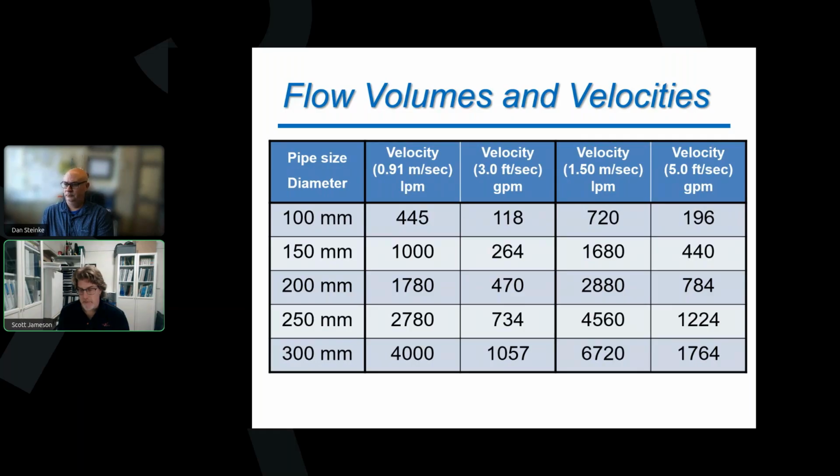You might have to bring in a water truck that is going to backfeed into your system through a hydrant or through a blow off, and give you that extra volume of water and some extra pressure to do that flush. So that's definitely one of the solutions that you can look at.